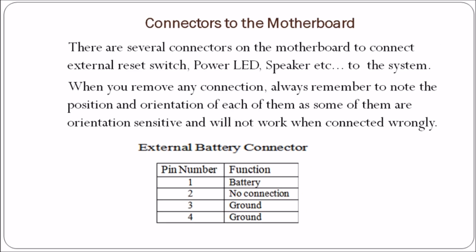Connectors to the motherboard. There are several connectors on the motherboard to connect the external reset switch, power LED, speaker, etc. to the system. When you remove any connection, always remember to note the position and orientation of each of them, as some of them are orientation sensitive and will not work when connected wrongly. This is the external battery connector. The pin numbers and their corresponding functions are given below.